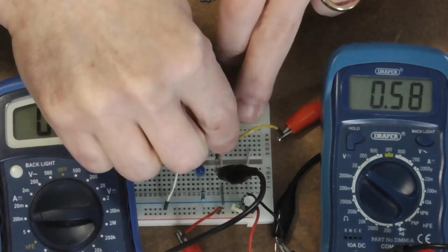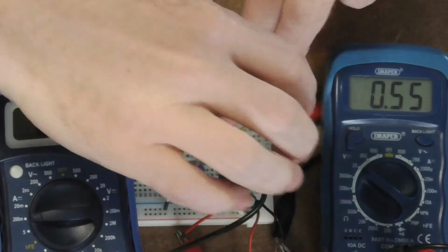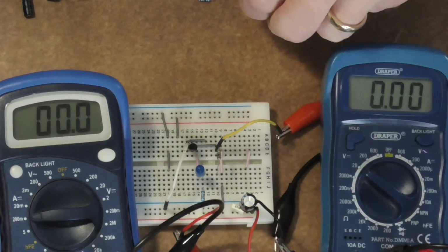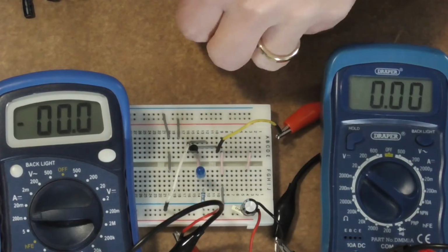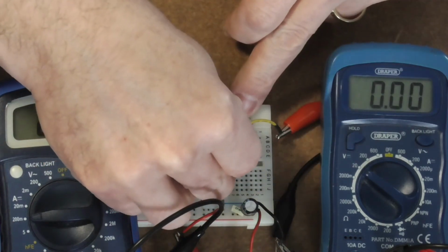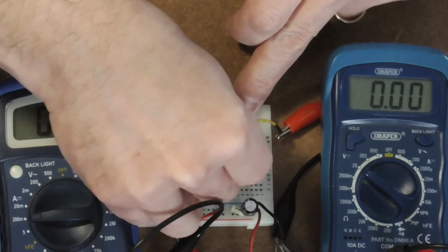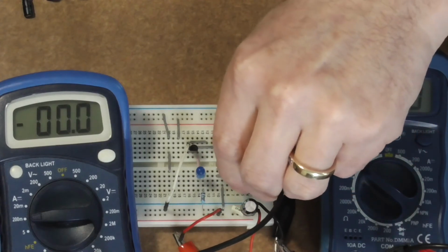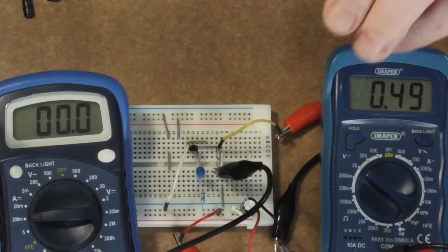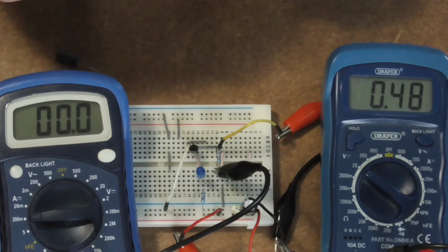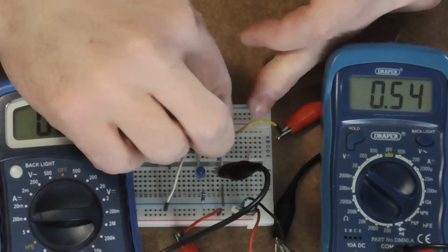Now what if I was to change the resistance, but this time I'm going to jump right up to the 100k and get this 100k resistor thrown in there. Connect up this multimeter, there we go, and we will start again with the, like I say, small capacitors. Let's throw the 47 microfarad in there this time, and it's quite a small one.